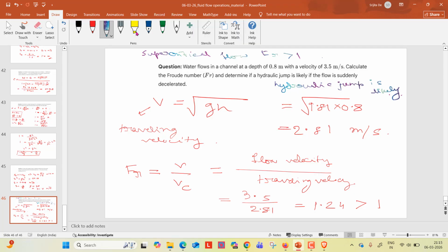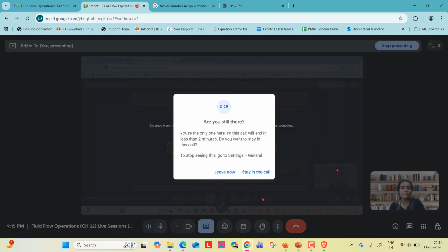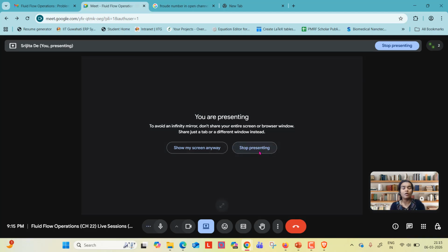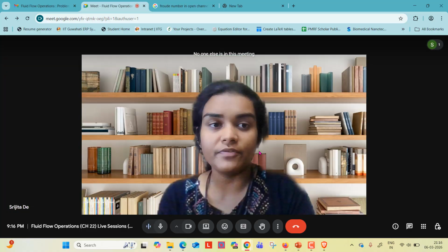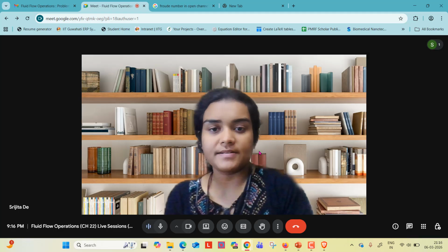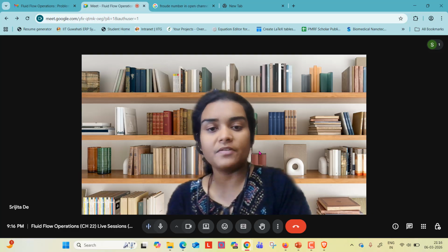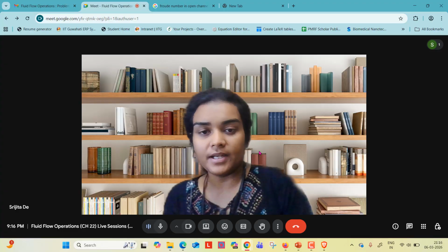So that's for today's class. I hope you have understood the basic concepts of open channel flow velocity, its maximum size or maximum dimension, and how the discharge and flow velocity can be maximized. You have understood how this leads to the zone of specific energy, the minimum specific energy and the concept of critical depth.